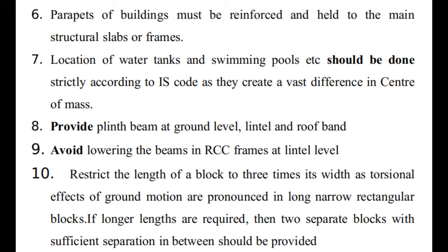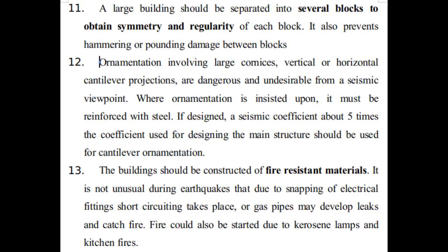Point number 10, restrict the length of the block to 3 times its width, as torsional effects of the ground motion are pronounced in long, narrow, rectangular blocks. So avoid designing long, narrow, rectangular blocks. But if longer lengths are required, then 2 separate blocks can be created with sufficient separation in between them. A large building should be separated into several blocks to obtain symmetry and regularity of each block. It also prevents hammering or pounding damage between the blocks.